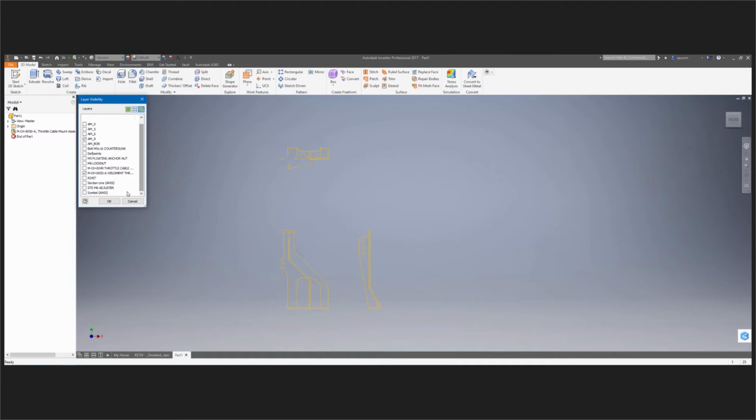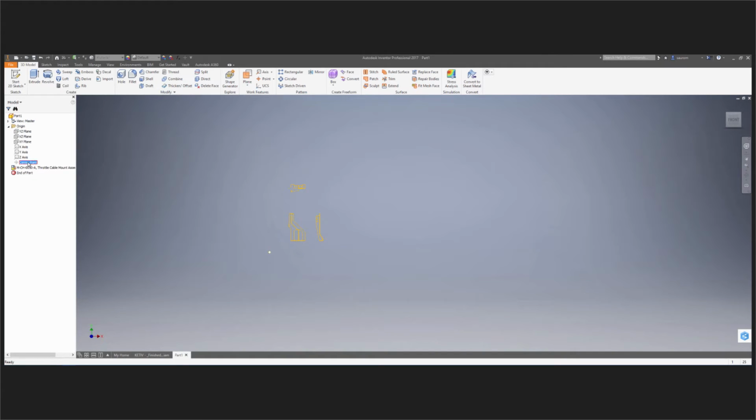I'm going to click OK on this, but if you notice, I'm going to zoom out a bit. My center point is a little bit offset. So what I'm going to do about this is translate this view. I'm going to say I want this to be positioned at that corner right here. It moves everything. Pretty interesting. So my front view is done.